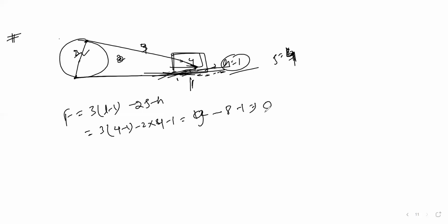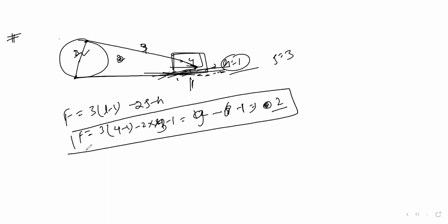No, there is something wrong here, because it's a mechanism. I think the number of joints is 3 here. If I take 3, then 3 threes are 9, 9 minus 6, minus 1. It's 2 degrees of freedom. So 2 degrees of freedom means there could be double rotation also, and it means the link is moving in more than one direction.